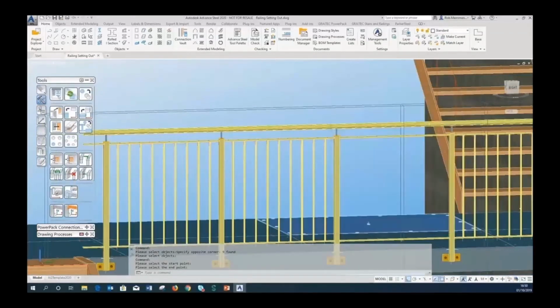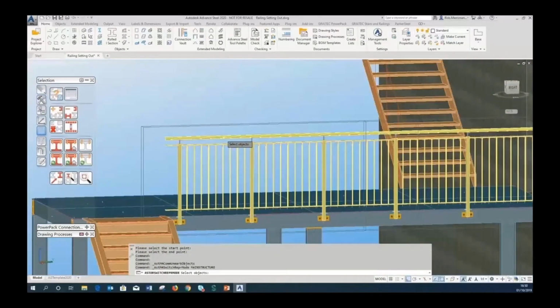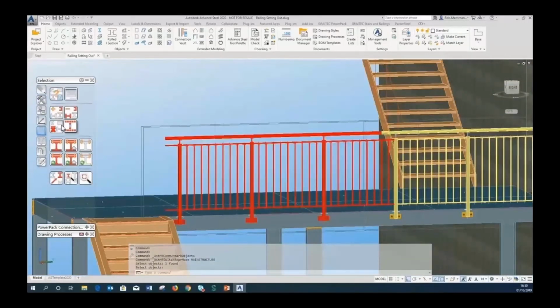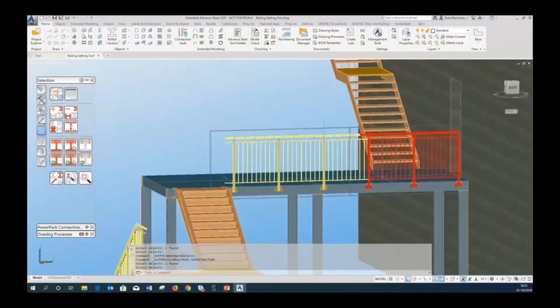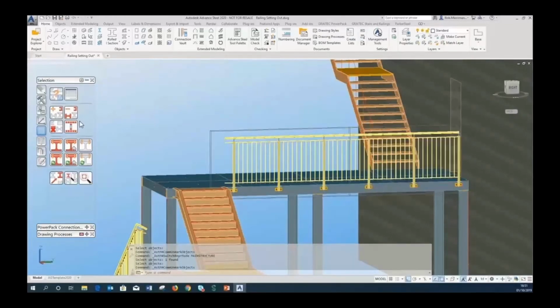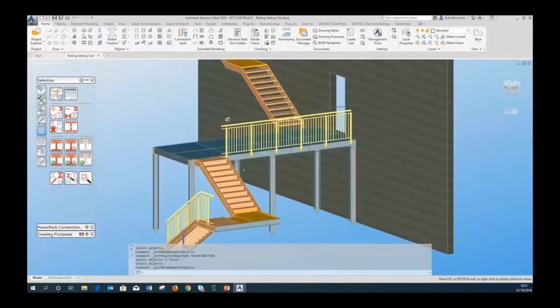And that's putting all those infill panels in. So I've manually copied them, but I've put them all in and they're still going to be welded up, and you can see they're still part of that railing. So I've not had to destroy the macro, the other railing's fine as well, ending at the right points. At no point have I had to destroy the macros, the joint boxes are still intact and they're still editable as macros. The only thing you have to do is adjust those infill balusters or pickets if you change the post spacing.